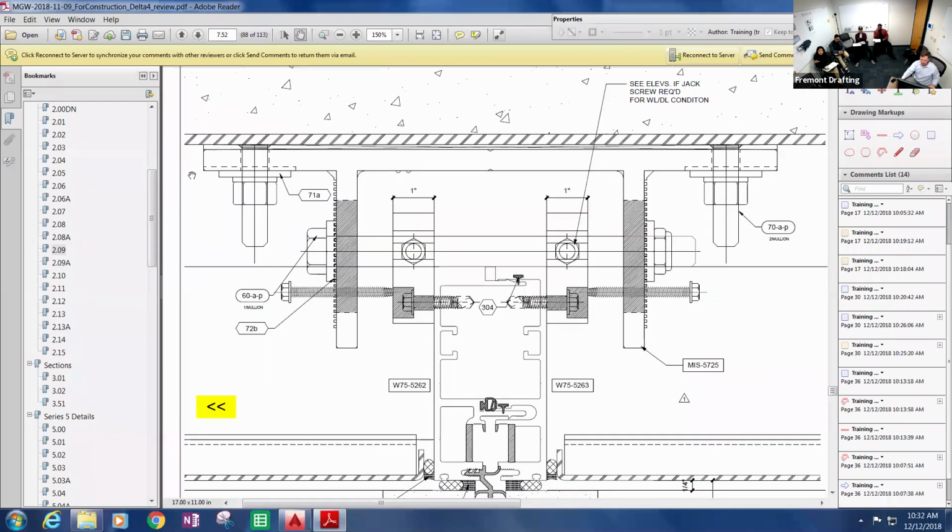This is the plan. Again, this is the bolt right here that's doing the adjusting up and down, and all the dead load is going through it. It's going through that into the 1-inch clip, back over into the 3 screws that are holding that hook lug onto this, and it's all bearing on this bolt. As our engineers look at that bolt, it's under dead load deflection, because it's getting the load. It's supported in 2 spots, here and here, and then the load's here.